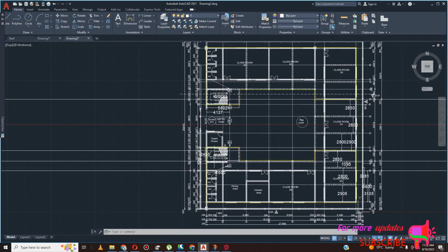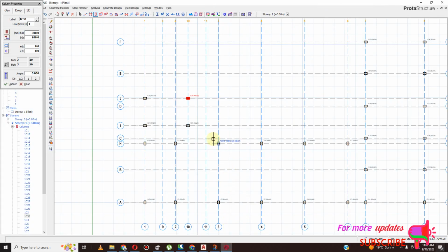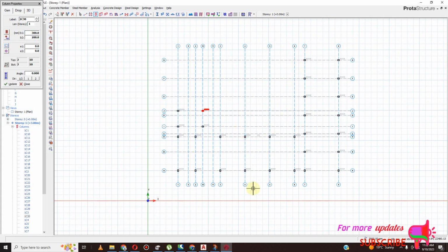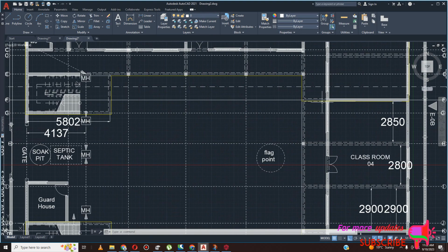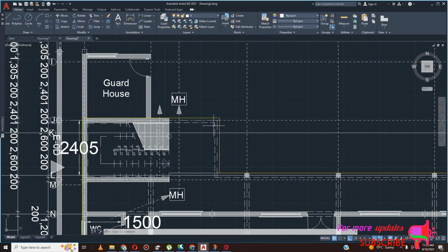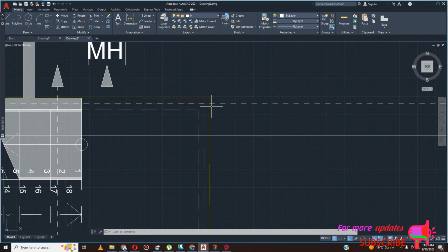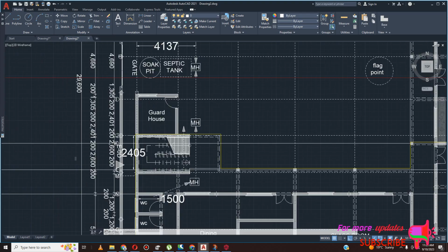Now here we have balcony. We have balcony. And I think here from the architecture specification, the columns for the balcony will not be braced, because these columns are basically meant to hold this balcony, which is too long, so it needs to be supported by columns. So I just put columns of circular 300 millimeters diameter.